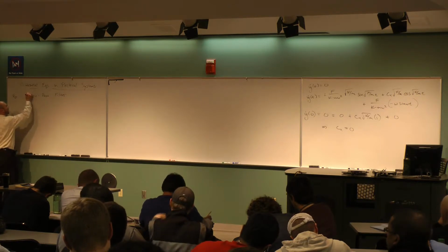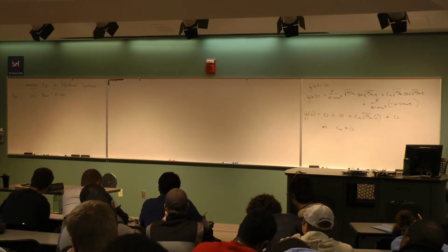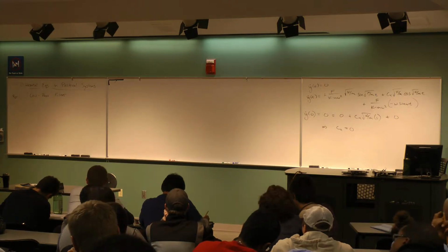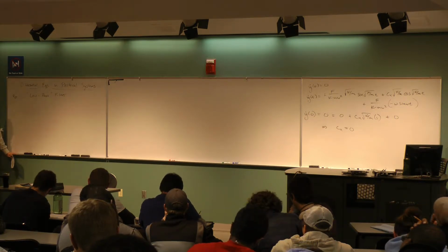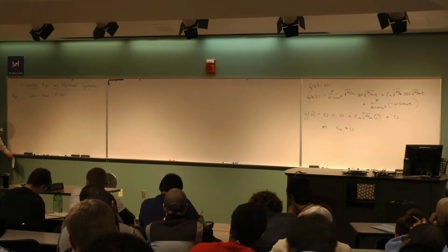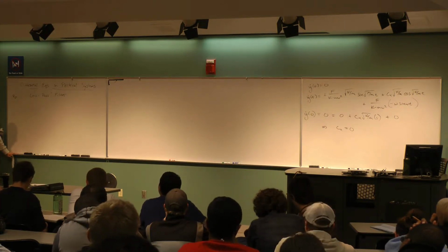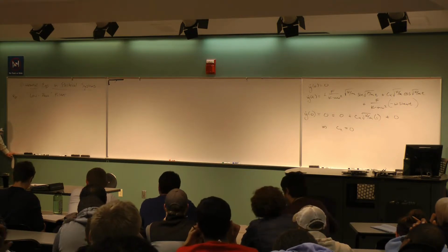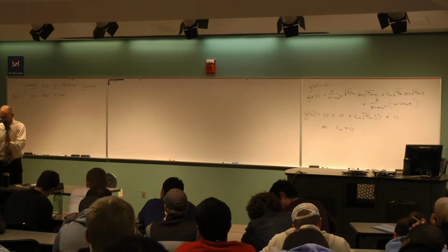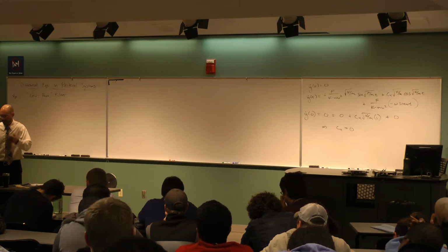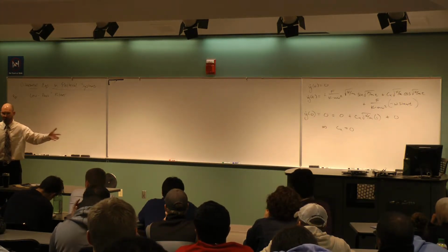Again, the idea is that in electronics, because we know that things like inductors and capacitors have derivative relationships, right? I equals C dV/dt, right? And for an inductor, V equals L dI/dt, right? So we have these input-output relationships. We can control rates of change of current and voltage by putting circuit elements in the circuit. When we combine them all together, it enables us to control signals that go through circuits. Any kind of electronics device is designed essentially to transmit electrical signals, right? And sometimes it's a really obvious application like an audio application, right? So I can put filters in an audio application to get a low signal-to-noise ratio, right?